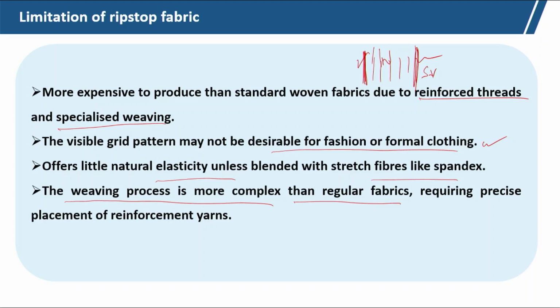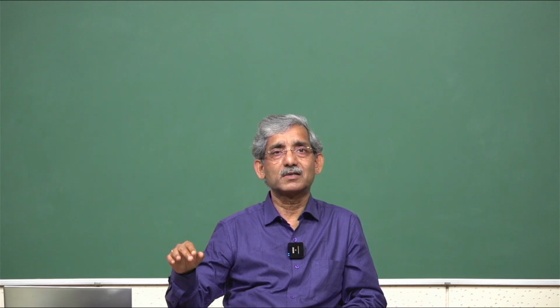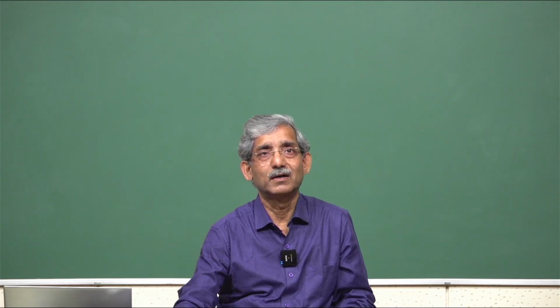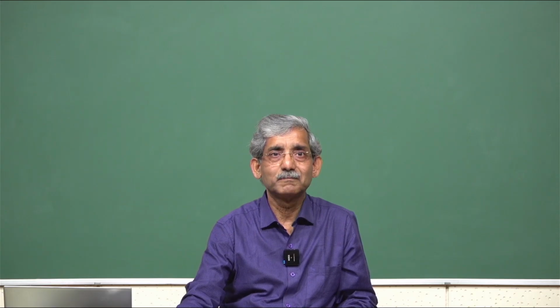So, during the shed formation, these yarns will behave differently. So, that will give a complex weaving process, and also in the weft, after a certain number of yarns, we require a certain pattern. So, that precise placement of reinforcement yarns during the warp formation and during the weft insertion makes the weaving process a little bit complex.